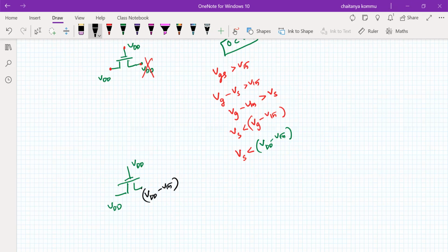For example, we can check again whether this condition is making this transistor on or not. Therefore, we know that VGS should be greater than VTH. And what is the value of this one, VGS? VDD minus VTH, right? So this is what we can say, and VTH. So these two will get cancelled. Minus threshold voltage, VTH is equal to VTH. That means the left hand side is equal to right hand side. It is greater than or equal also.